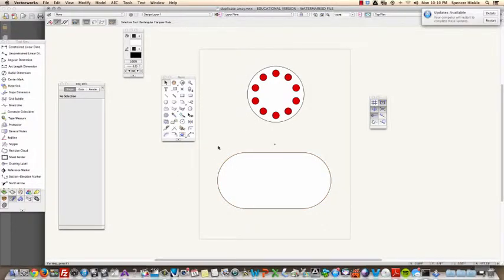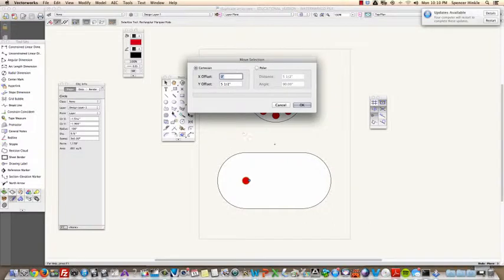All right, so now let's do our radial or our circular array first. And let's steal one of these circles up here and we'll bring it down. Now it's important where you put this. And a really good way to position this thing is go to the arc center. So let's move it up. Command M. And let's move it up. We don't want to move it at all side to side. We want to move it up 1 1/2 inches.